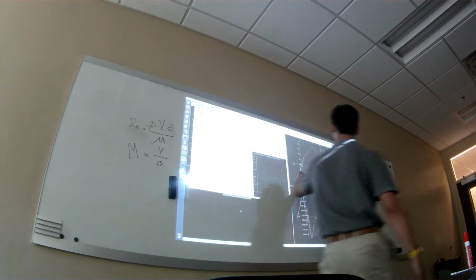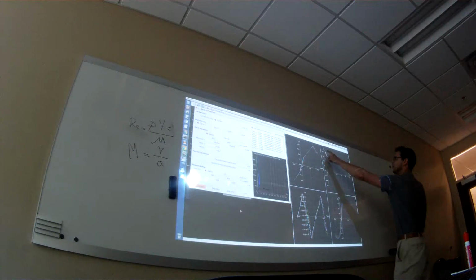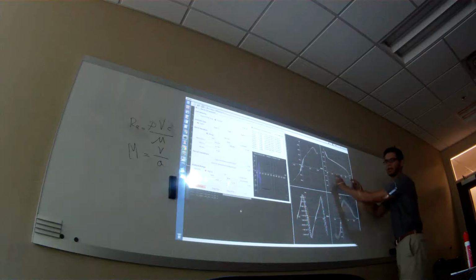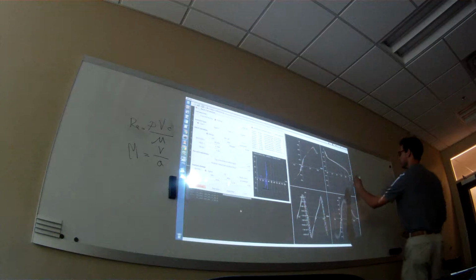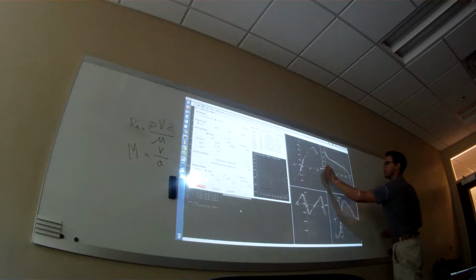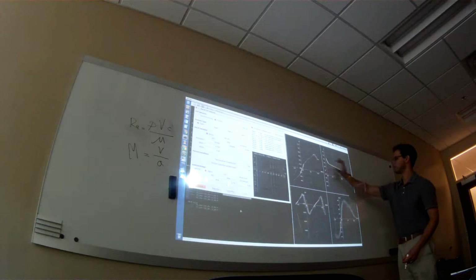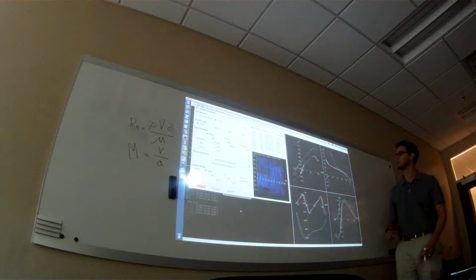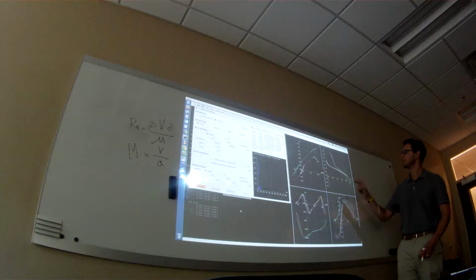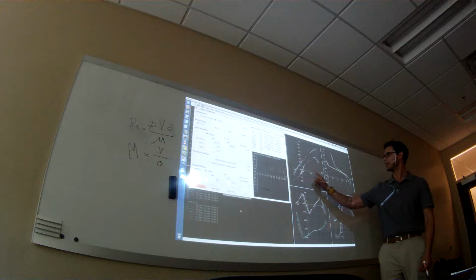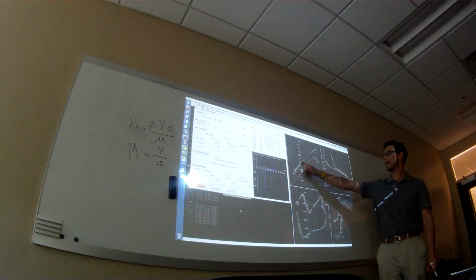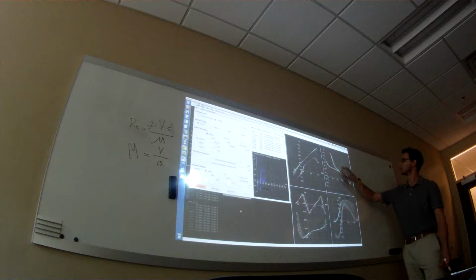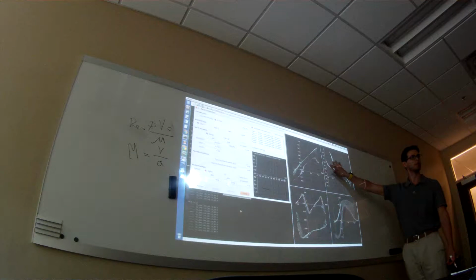And if you notice, it's plotting CL versus alpha. This is lift as a function of angle of attack. So imagine that the wing is sitting right here, and the flow is moving this way. So this is how much lift I'm getting here. I've got my lift to drag slopes here. I've got my pitch moment slopes here. And I think this is doing it for 2 airfoils. So if you notice, this was the symmetric airfoil, so at an angle of attack of 0, I've got no lift. But for my cambered airfoil, at an angle of attack of 0, I do have lift, right? Because it's cambered. And you'll notice that the lift distribution is completely different for the 2 wings, right?